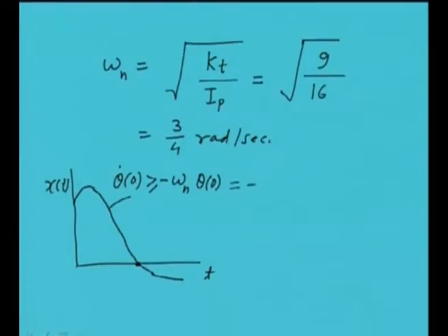Here we know the natural frequency, we know that maximum opening of the door is 60 degree, so that is pi by 3. So this gives us pi by 4 radians per second as the angular velocity of the door if we give at the initial maximum position of the door. It may just not hit the door. So this is the minimum. If we give more than this, then it will hit the frame, which is not desirable.